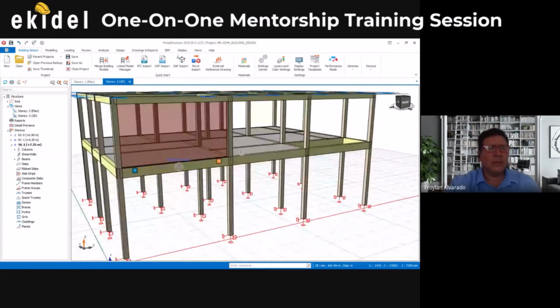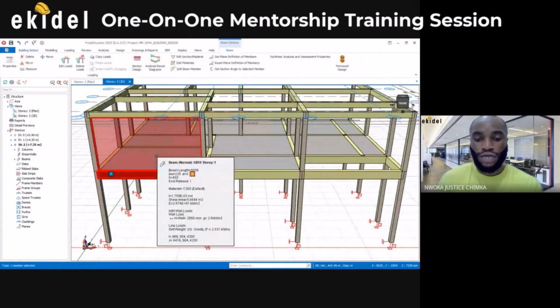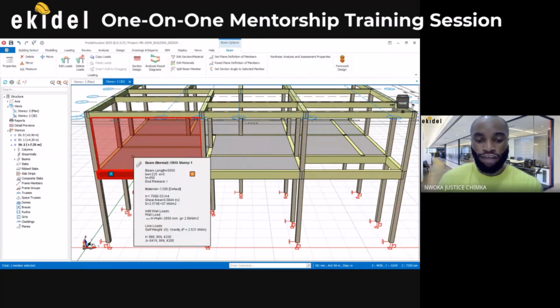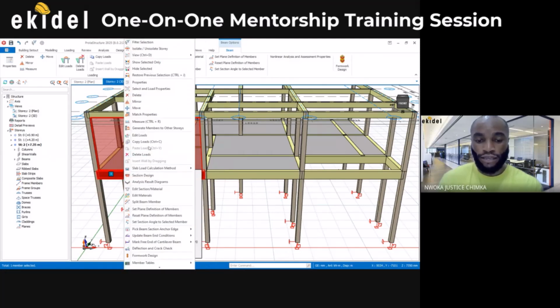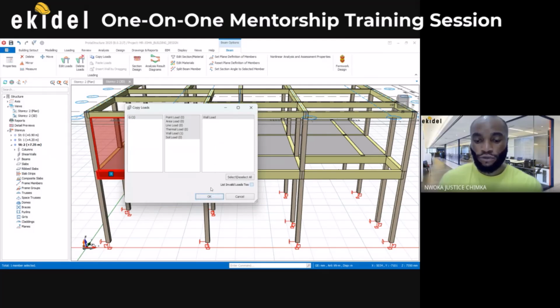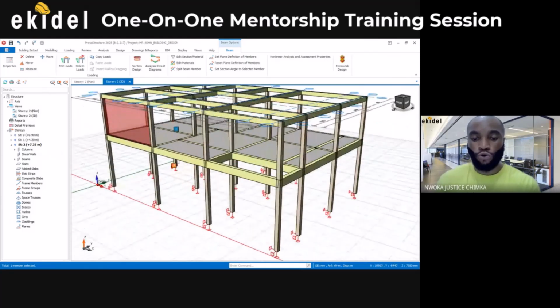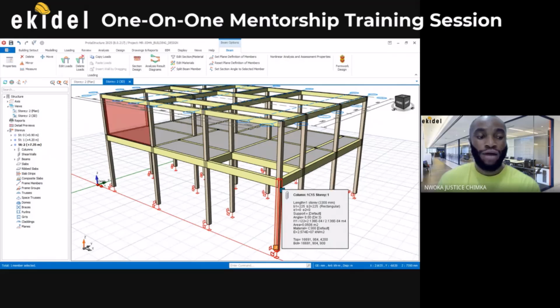Can you see that? You then click on this load and copy it. Right-click on the one that has load now and say copy load. Copy load. You just say OK. And then we want to add wall load to all the beams. Then later we can check the ones that don't have wall load.